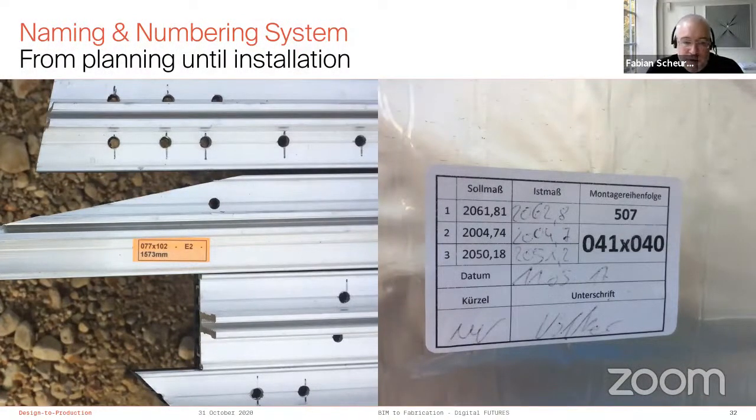And one other important thing that really happened very early on is that we agreed with everyone on a common naming and numbering system for the overall structure. So all the facade elements all have a number combined of the 2 beams where they start. In this case, it's 41 cross 40 are the 2 beam numbers, and this is where the facade element is. And to the very end, 6 years later, every little aluminium profile was basically named and numbered after the system. So you could pick it up and actually know pretty quickly where in the overall structure it would belong to.